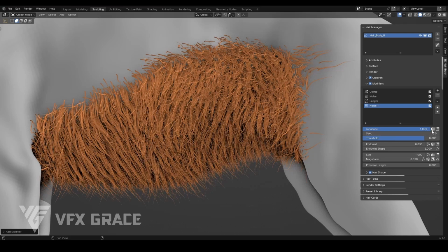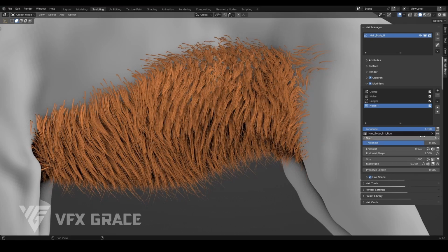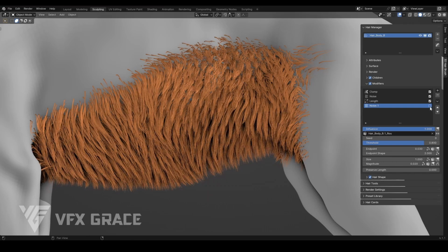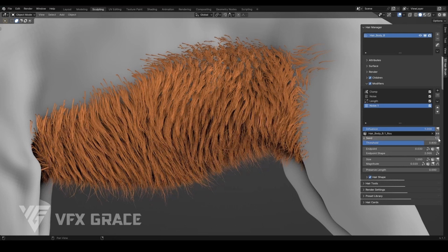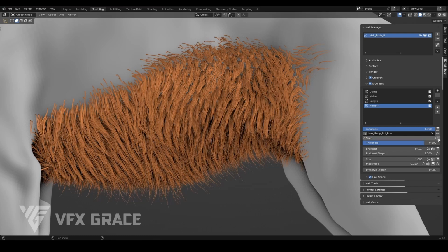Also, we can use vertex groups to control the randomness intensity in your desired area. After adding the vertex group, turn off the modifier and compare the effects before and after. Adjust seed if the region of random long hair needs modification. We've created the stray hair, then how can we control its length precisely? Here we provide a method where you can use one more length modifier to control it conveniently.